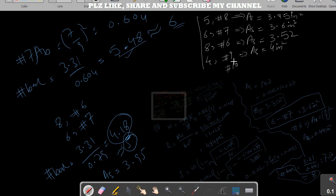If I divide 3.31 by the number 10 bar area, 3 number 10 bar will give me an area of steel which is 3 times 1.23, which is 3.69 square inches. So from all these options, the best one is this one, 3.52, and the second one is this one, right, which is close to 3.31.